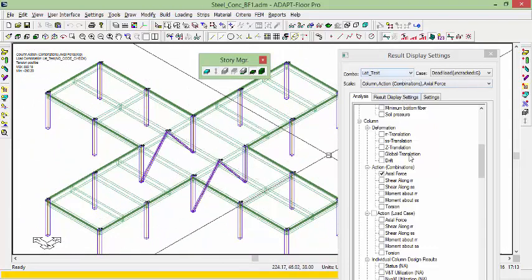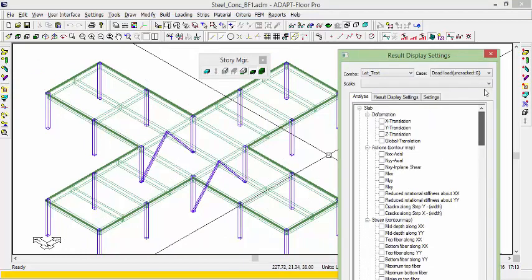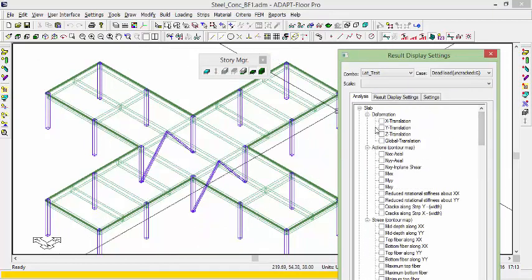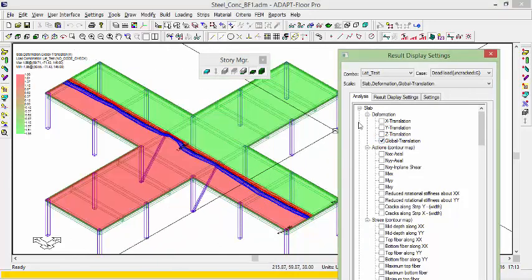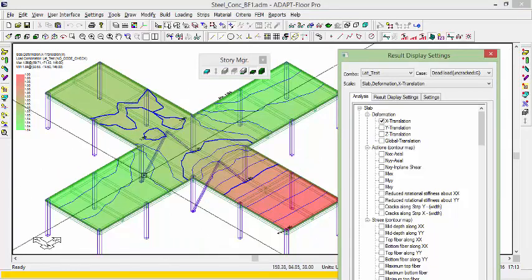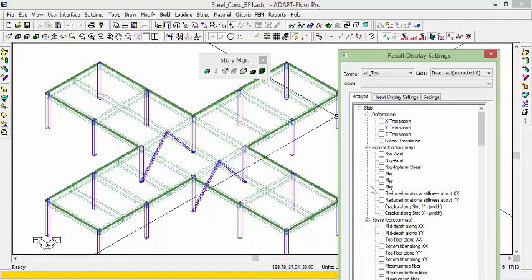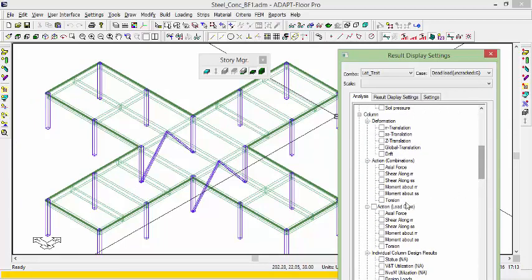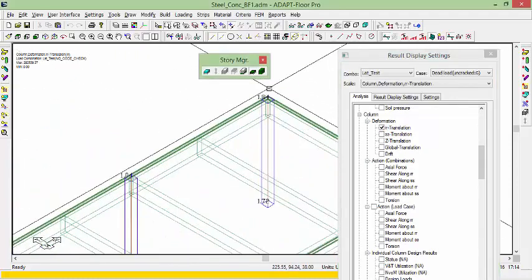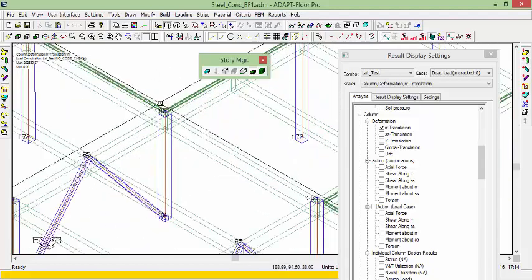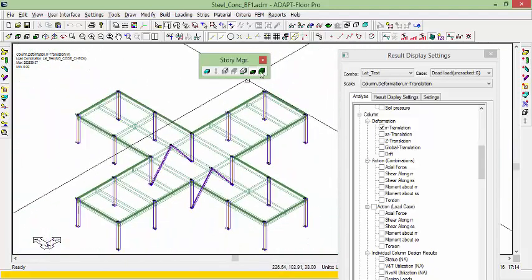All of the action is really happening here in the braces and the column towers that are connected to the braces. So additionally, if we wanted to check deflections for any slab, if I go up to the top and I select the option for deflections, for example, the global deflection or the X direction deflection, we can see the different contours deflection-wise at a particular slab. We can also use the options for component deflections. If I scroll back to columns and I look at the RR or SS translational values, we can see deflections at particular locations, top and bottom of columns at this particular level. Globally,